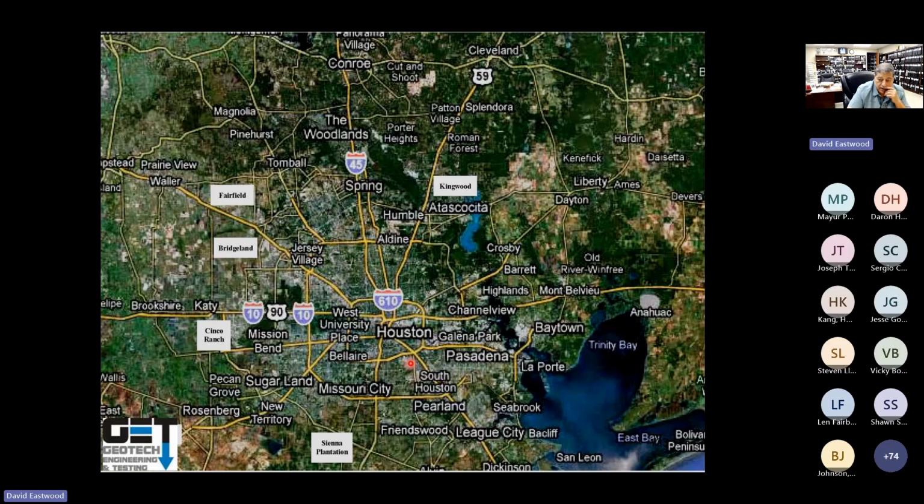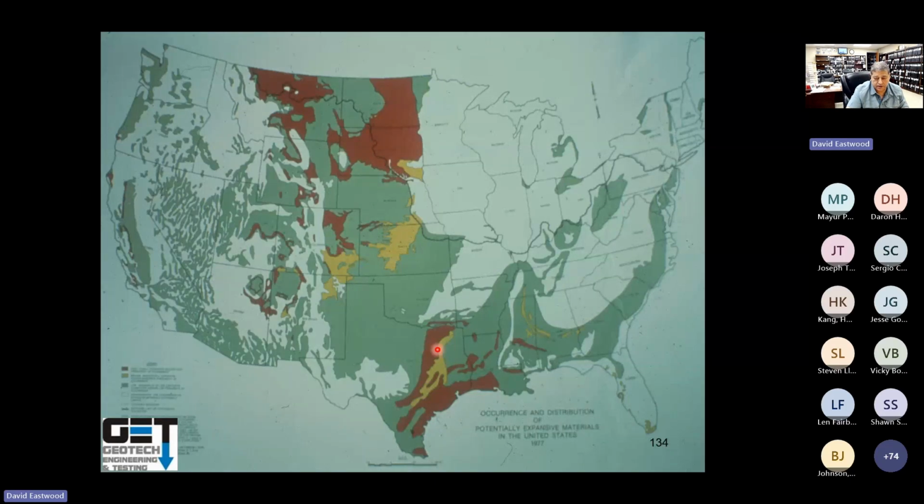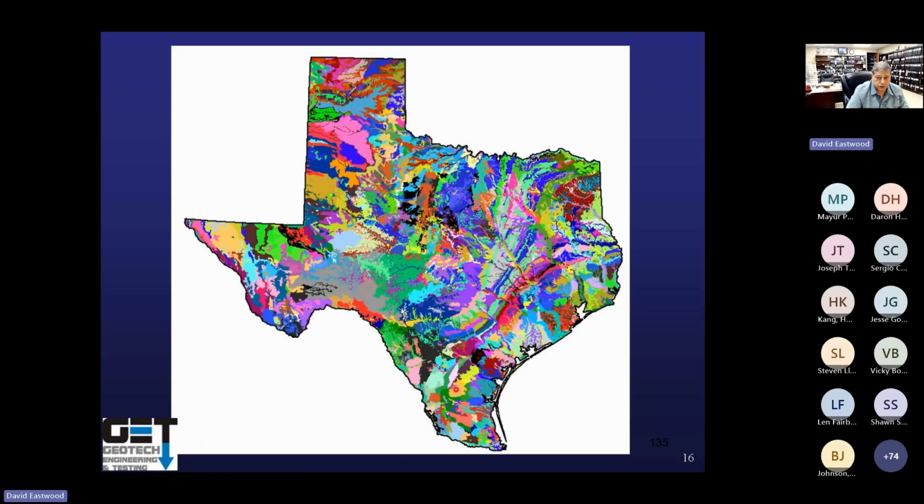And so you got different types of soils around Houston. Of course, it goes with everywhere around Texas. You're going to have different types of soils. You go around Texas, you will see fat clays in these areas of Texas and Louisiana. Texas soils are variable, so you got to know what kind of soils you have. Again, if you have rock, you got the best subgrade. So your 6-inch paving would perform very good on top of a rock.